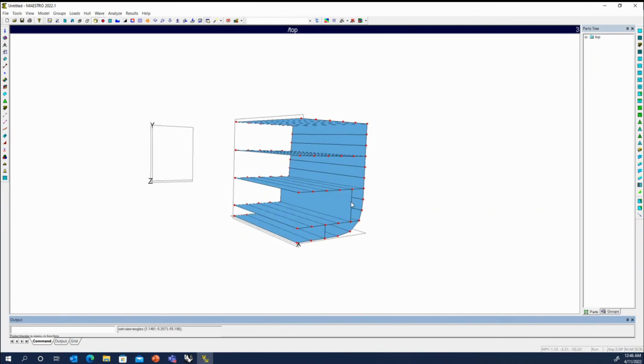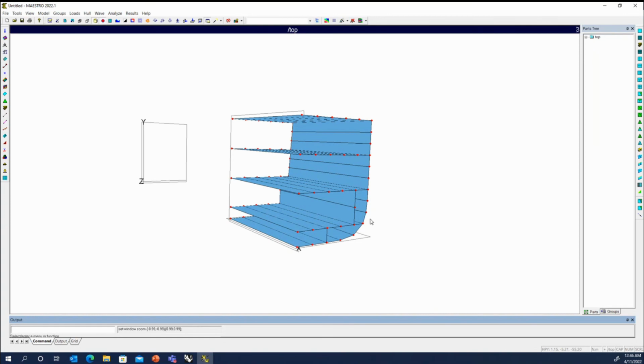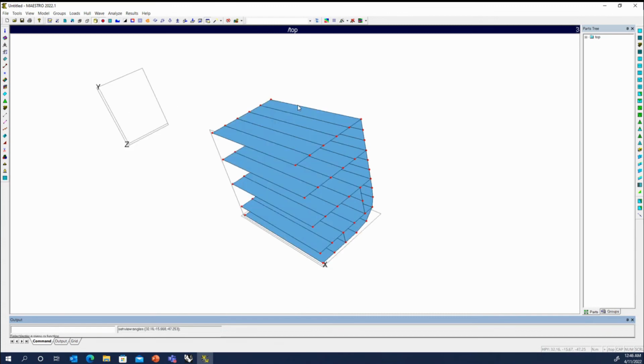Now this strake was a little large, so we'd probably subdivide that one. We could have done that either in Rhino, or it's easy enough to split a strake here. So we can do that here. We can split it again and then line those up with the other strake points if we want. It's a flat bulkhead, so it's nice and easy to manipulate the heights of that one. But then you can see strake element, the entire length of the module.